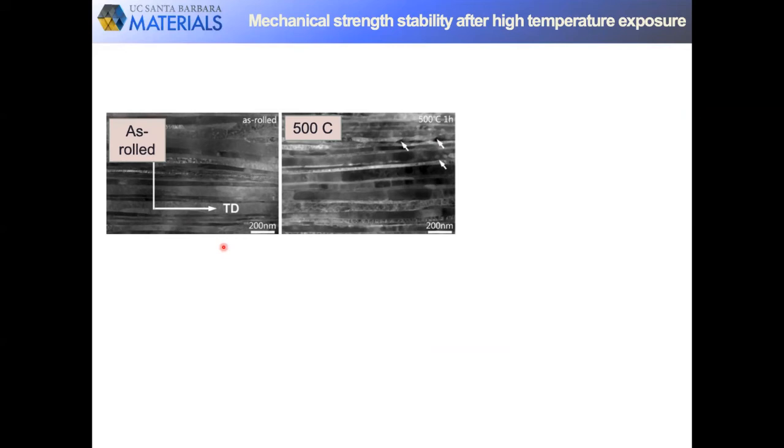Earlier, those were hardness tests, or post-anneal hardness tests. With these nanolayered sheets, we can now test for their performance after exposure to temperature. So we separately ran some tensile tests for these nanolayered sheets after temperatures ranging from 400 degrees C up to 1,000 degrees C, so dangerously close to the melting temperature of copper.